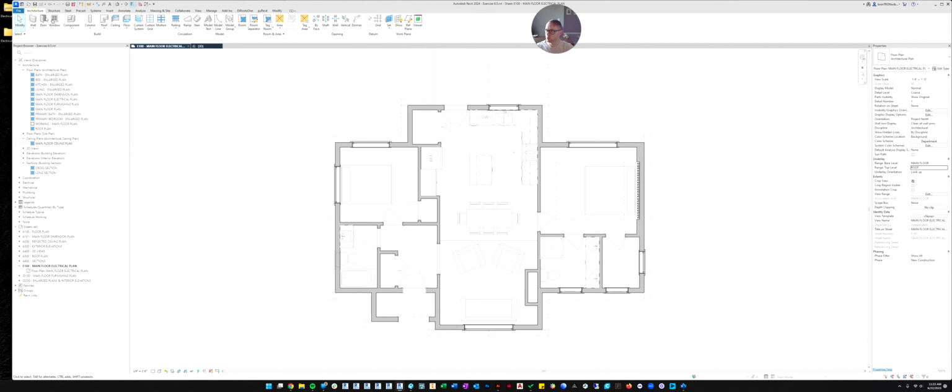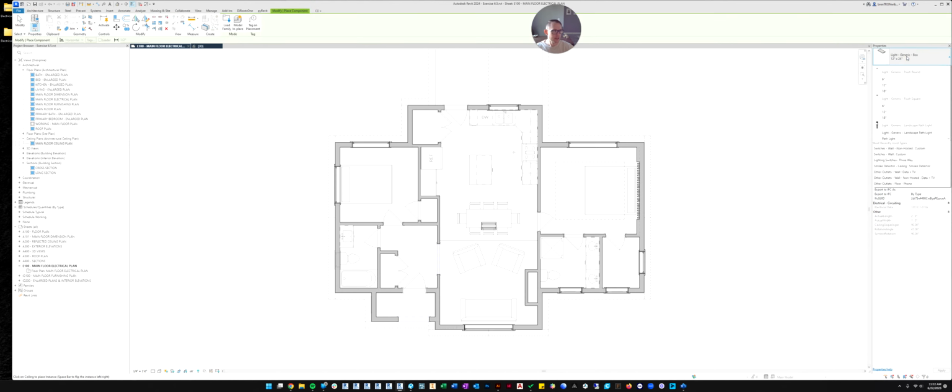Let's go to the component command and let's do outlet. Oops, you've got to spell it right. Let's do power outlet. Maybe, I can't remember what it's called. Let's start with outlet then. Data outlet. Oh, electrical outlet. So that's what we're looking for.